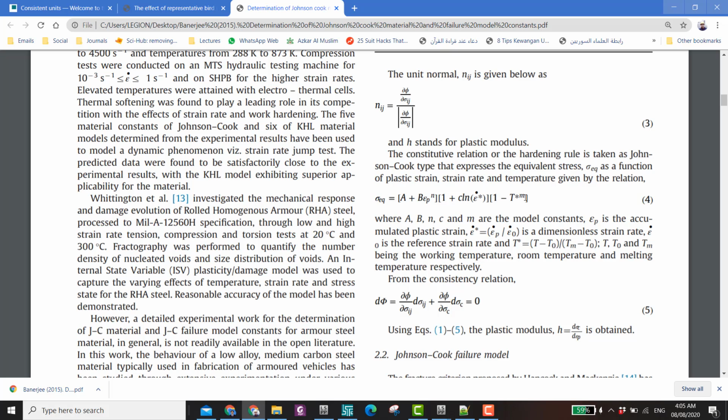But in our problem we don't actually need the effect of the temperature. This bird strike is going to be a dynamic problem, and the strain rate is very high, and when the strain rate is high, this will affect the material properties, and that's explained with this epsilon dot here, which is the strain rate, which influences the material model.